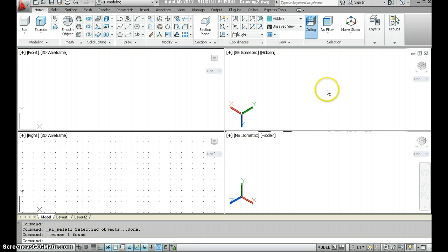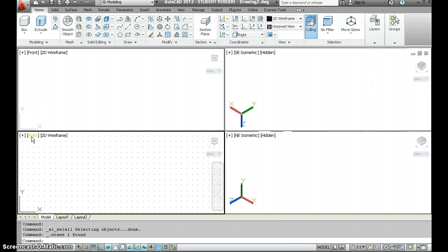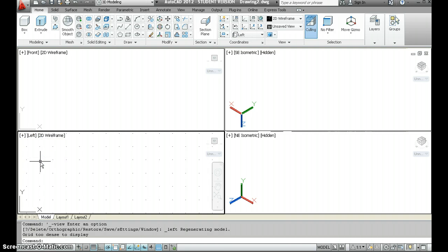This is exercise 4 in 3D AutoCAD, and for this exercise we'll keep the front view in the top left viewport, but I'll change this to left view, although it doesn't really matter, but just to have the same configuration as is in the drawing, in the handout. We can start this in left view by drawing the trapezium and then extruding it by 40.